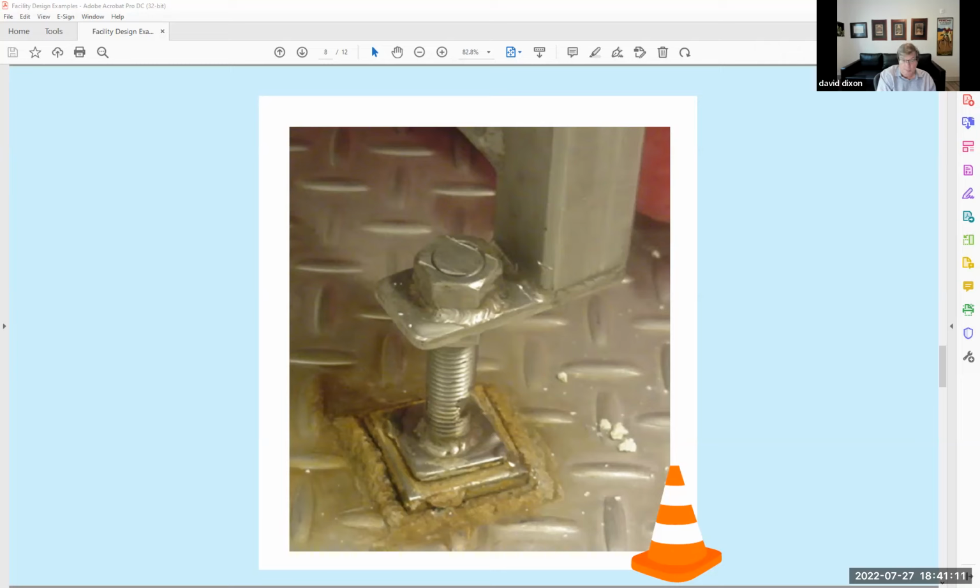Right. They don't look like this. It's usually stainless, and it's a one-point contact. It's not a flat plate. There's a lot of detailing that the equipment engineers are used to. But take a look at how all of your equipment sits on the floor and whether it creates a niche below it. Really important points.